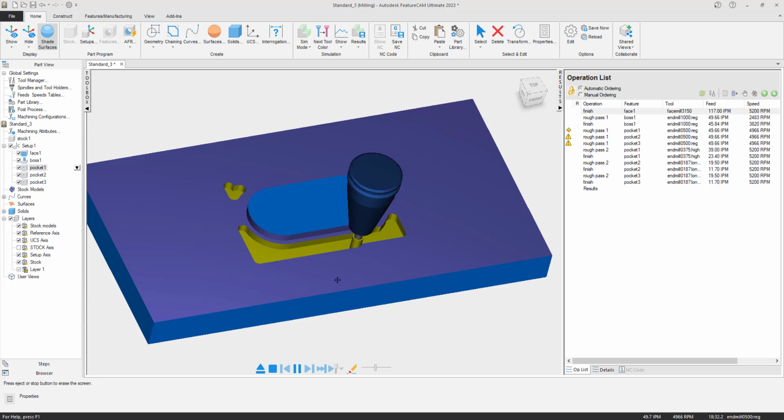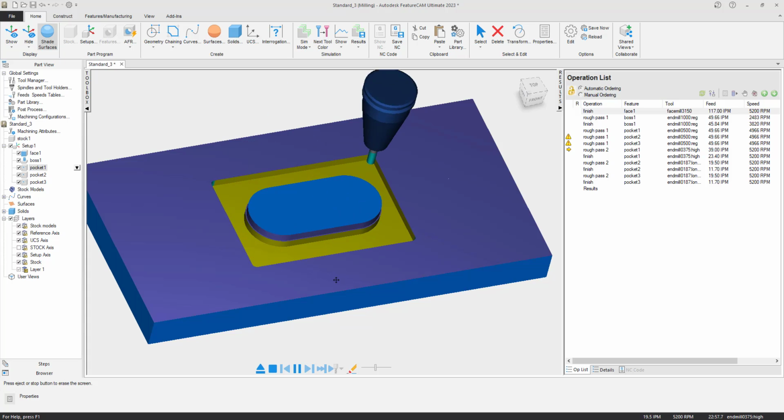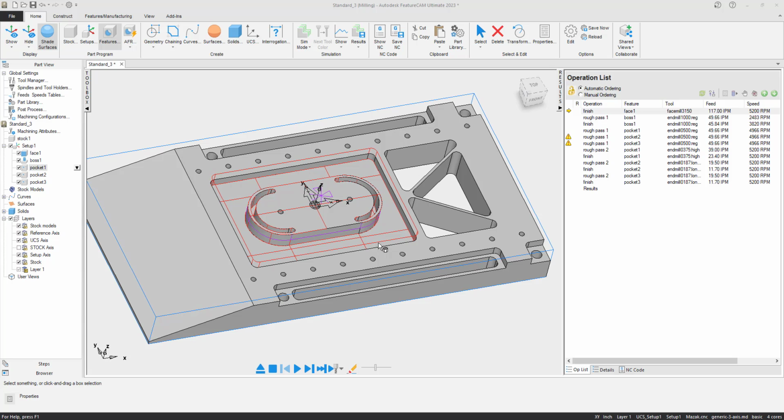So you can see that it's going to start doing its pocketing, and then it'll start doing those half moon pockets. And notice I don't have any hot pink showing up, which means my shank of my tool is not hitting. So in that first tutorial we did, I went over how to establish that and how to keep it from happening. So I'll hit eject, and we're almost through this whole part.